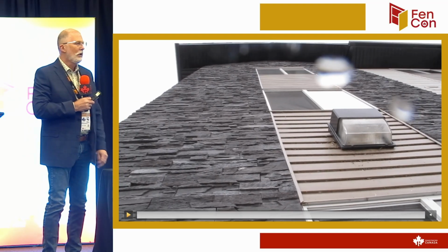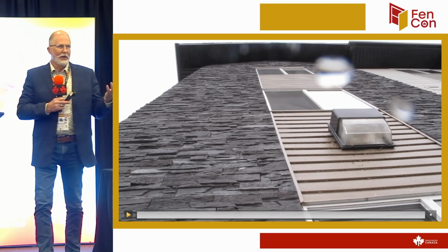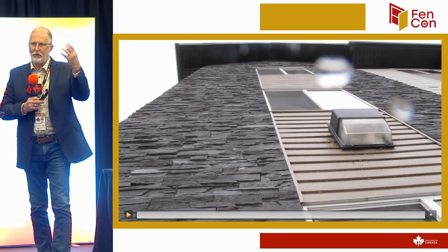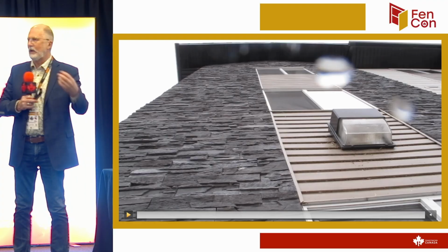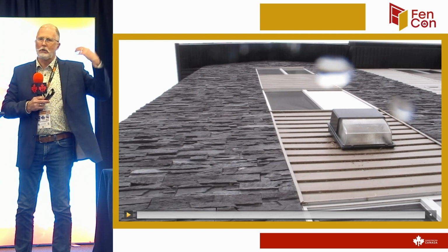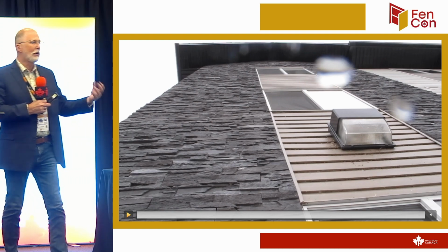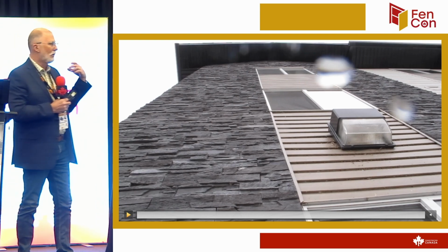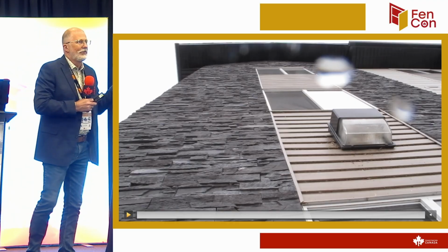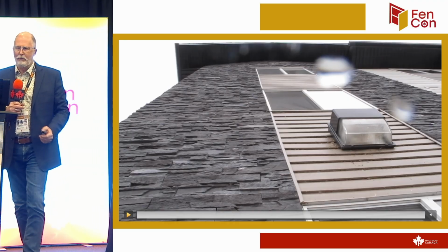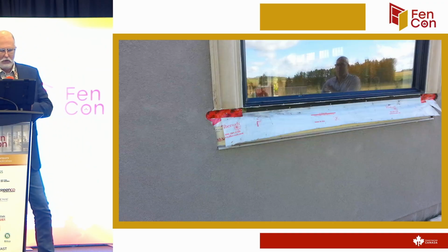Everywhere there was stone. So, you know, the rule of thumb in terms of balance is you want to let a certain amount of water in. It's fine if it gets wet, but you want to have an equal or greater amount of ability to get rid of that moisture or dry it out, because otherwise this is what happens. So this is kind of what got me into pushing for code change.